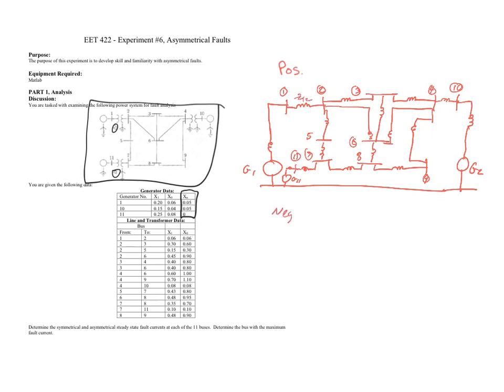To draw the negative sequence diagram, it equals the positive sequence diagram. The only difference is we actually subtract the power supplies. Those will not be included in our connection diagrams here. So those have no place to show up. So essentially, I'll sort of circle or highlight here which ones those will be turned off, set equal to 0.